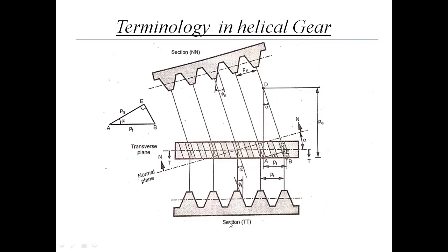Transverse plane. This is a transverse plane, TT, the plane of rotation, and that TT is perpendicular to the axis of rotation. So you can see the sectional view along the transverse plane. It is the corresponding point on the adjacent teeth, measured along the transverse plane.